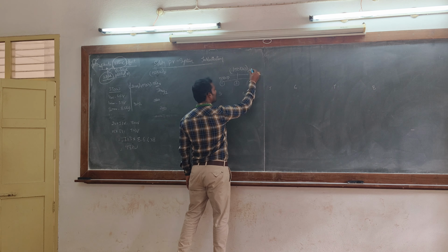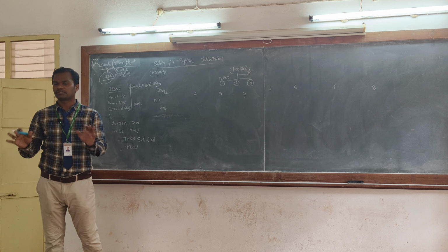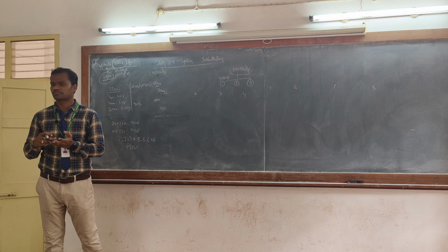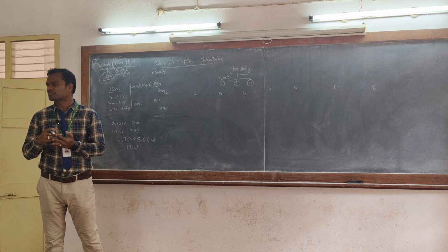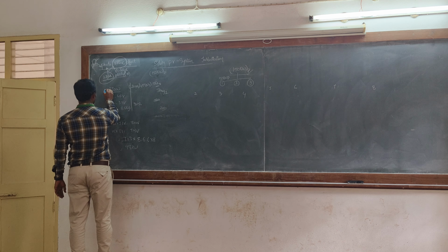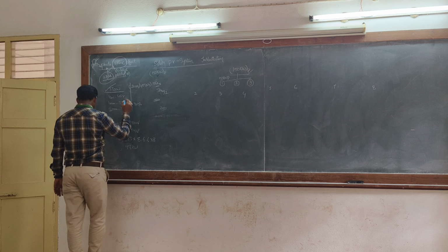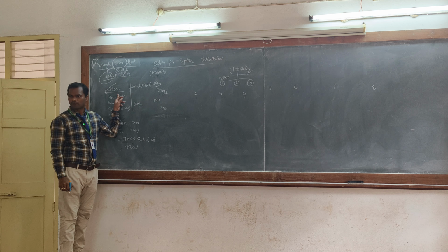Now we are going to analyze this 150 kilowatt solar power plant with respect to number of panels, open circuit voltage, maximum voltage, and maximum current. In our campus this plant has been developed. The rating of this solar panel is 330 watt peak.